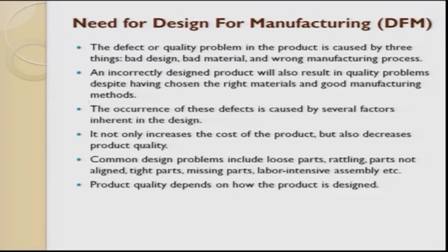The first one is commonly used for small batch quantities, and the extrusion process always looks toward mass production. In mass production the die cost is very high, so in order to recover the die cost, they always look for mass production. The component price also comes down drastically, and it is also a very good process as far as the environment is concerned.